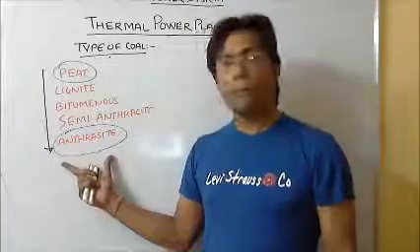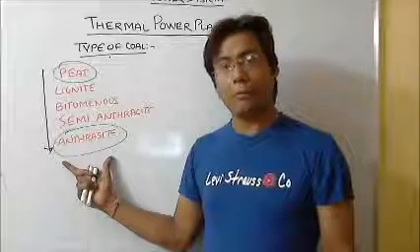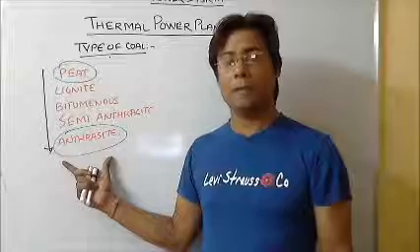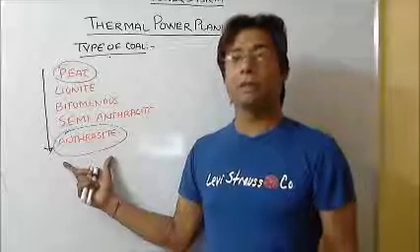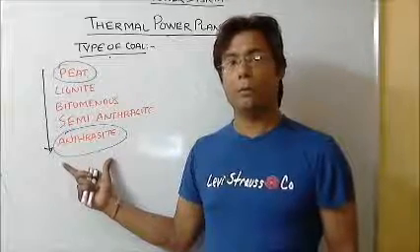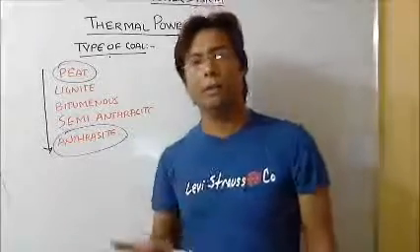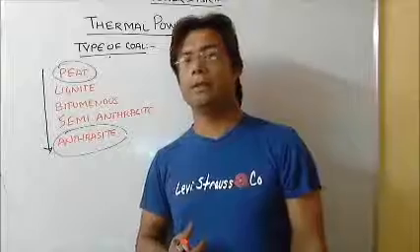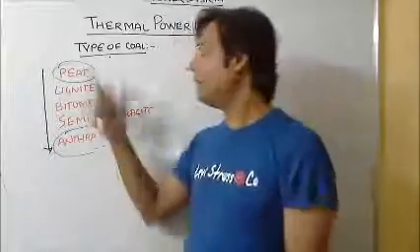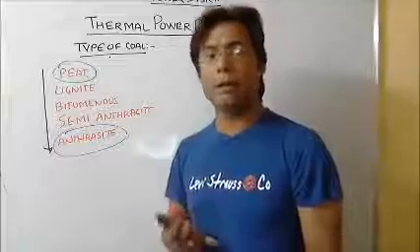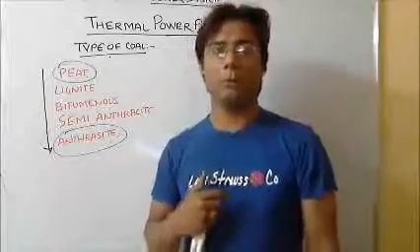So this will be giving more energy or more heat when burning, and when it gives more heat, more water will be heated up, more steam will be generated, more electricity will be generated. Whereas the peat will not be giving so much heat, and that will be deteriorating the efficiency of the total thermal power station.